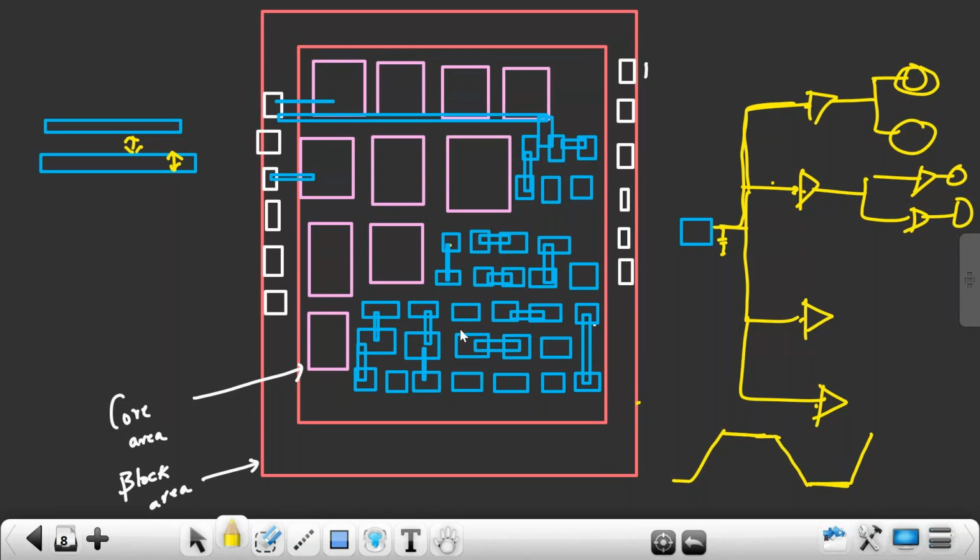Okay, with the mux I cannot meet the timing. Then change the cell. Instead of mux, use AND gate and OR gate and try whether I can meet the timing. So it will do logical restructuring many times. Why is it doing logical restructuring? To meet the timing. To meet the timing, what is required? I need the cell delay and the net delay.